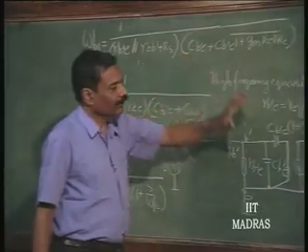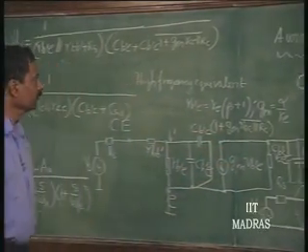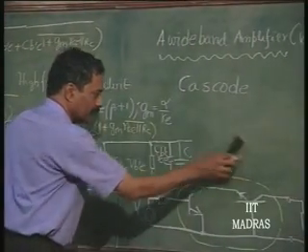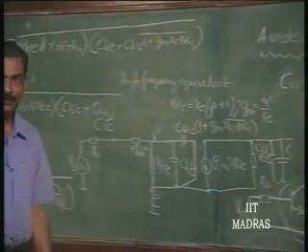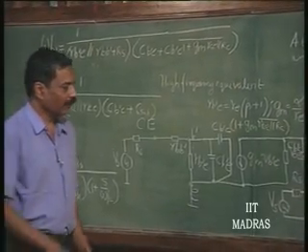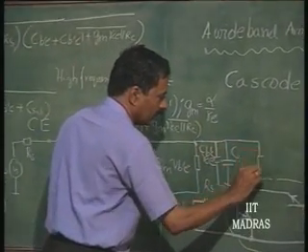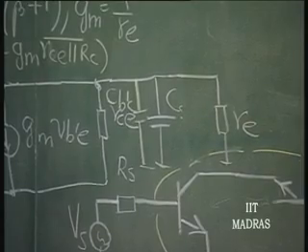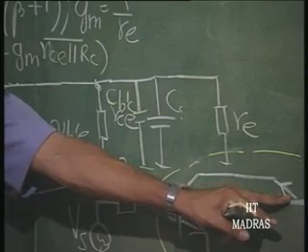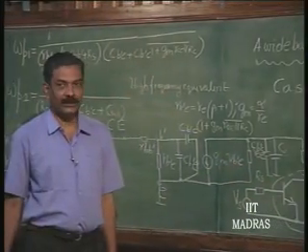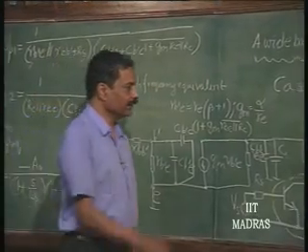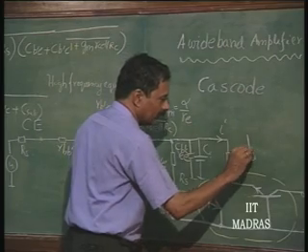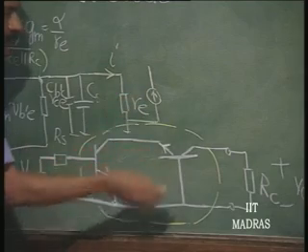That is why we had gone for a Cascode structure. What happens in a Cascode? All these things remain the same, only thing is now there is no R C here. Instead of this R C, we have here just about R E. That is a common base structure. Okay. The resistance here is R E very nearly. So, it is almost a short circuit at that point, and if this is the current I, then the current here is going to be, that is the equivalent for the common base.